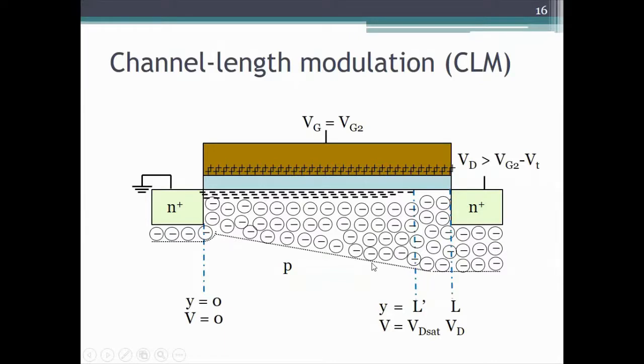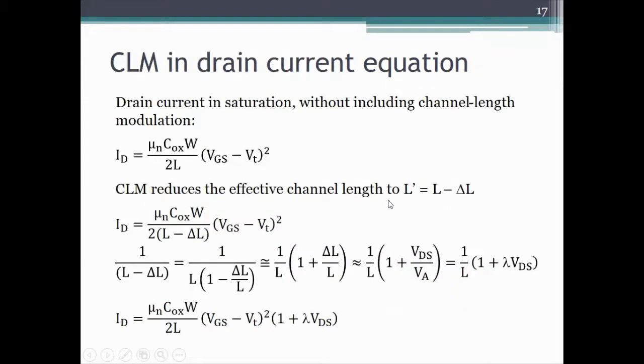Okay, so this is the figure we have seen before. This is of course for a long channel, and it is pinched off here. Again, what we call pinch off here, we could think of as a velocity saturation region for a short channel MOSFET. So let's derive an equation for channel length modulation, very quickly.